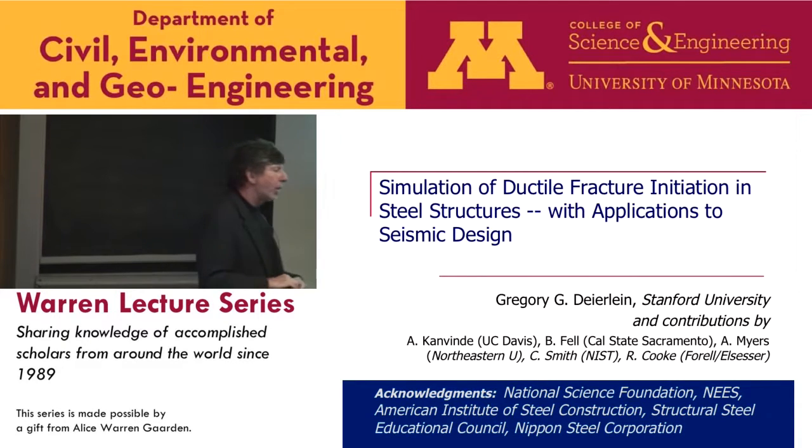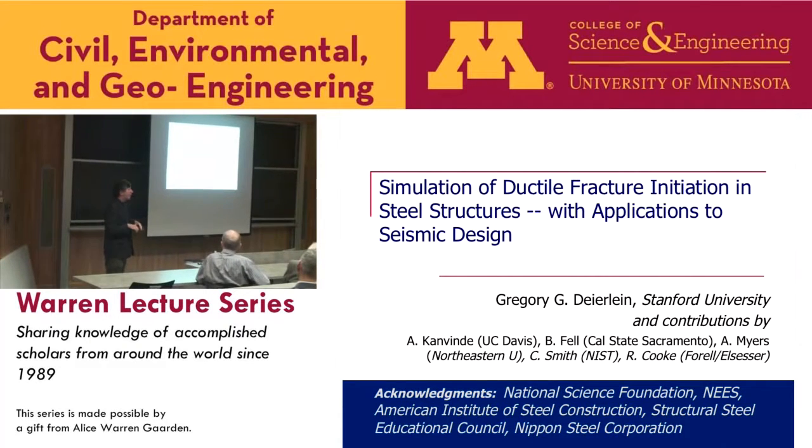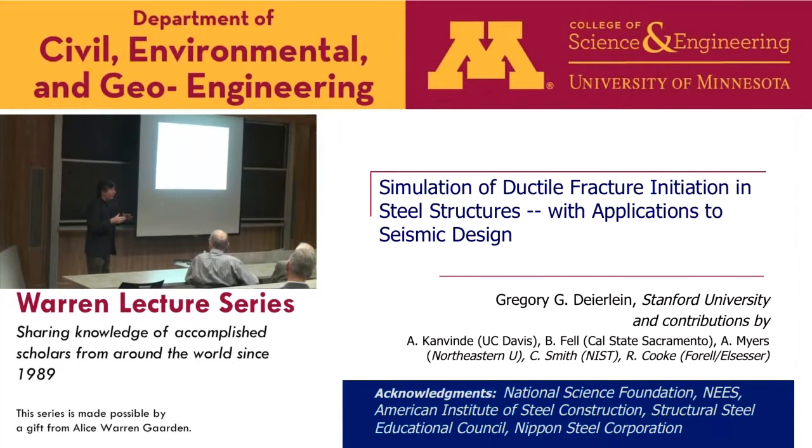Well, we've thought about these models being applied to a bolted connection. And you'd say, well, why would I do that? Because we like our design models, looking at net section and a thin plate. They work pretty well because, if all bolted connections were thin plates with not too many bolts, the net section works well. But suppose you have a really long bolt group, where there's unequal stresses going through it, and suppose you have a pretty thick plate where the stresses and strains aren't the same through the plate.